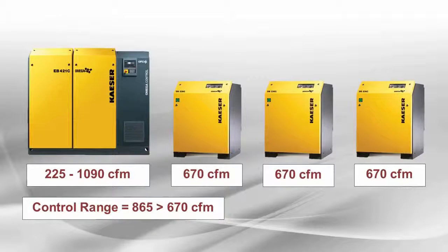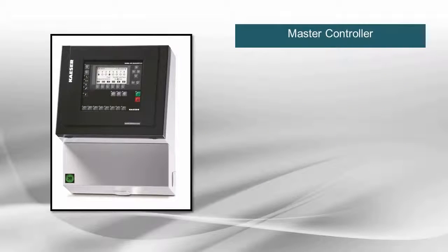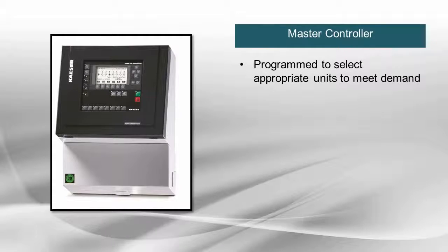Properly sized machines can be placed in a short idle or standby state for rapid response to varying demands. A machine in idle will use far less energy than a loaded machine venting unneeded air, and will use no energy when turned off. Choosing energy-efficient blowers is important, but the critical element of this solution is an adaptive system controller. This smart device is programmed to select the appropriate units to bring online to meet demand most efficiently, based on an input signal, such as dissolved oxygen level.